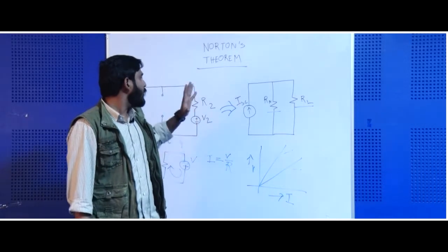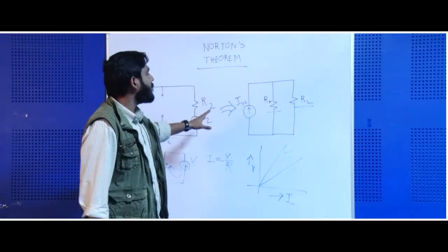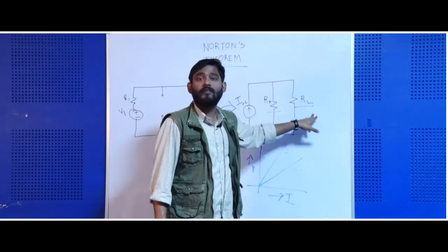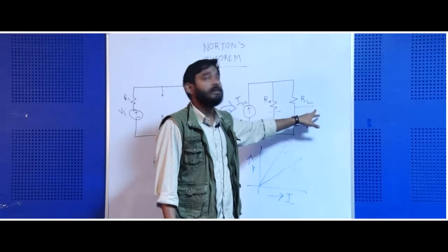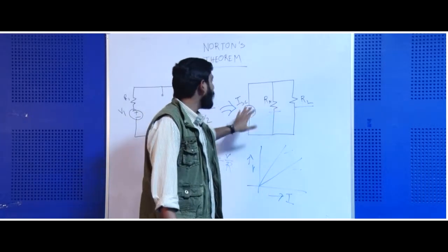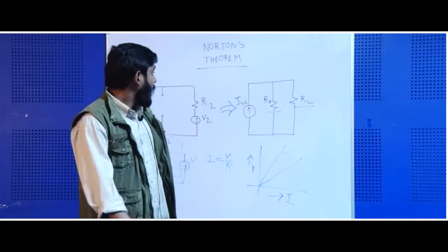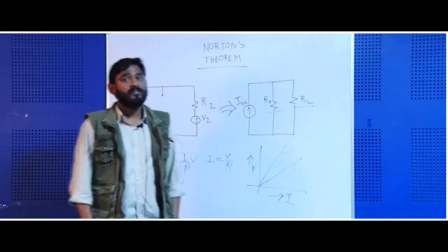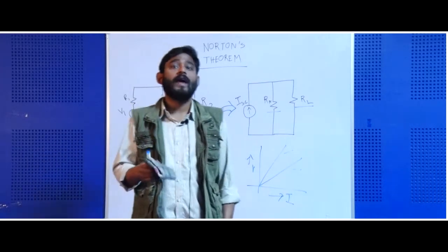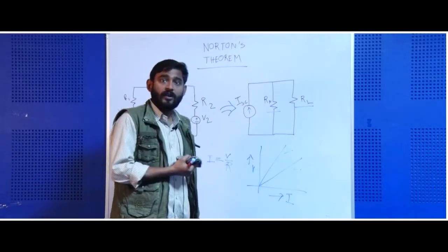Now, we have to do certain calculations so that we can ultimately try to find out these 3 parameters. See, in this case already we have found out the first parameter of our necessity, the RL, you know what is the value of RL. Next is the RN and the ISC. Now, how to calculate RN? RN is the total internal resistance of the circuit, and there is a particular method to calculate the RN.